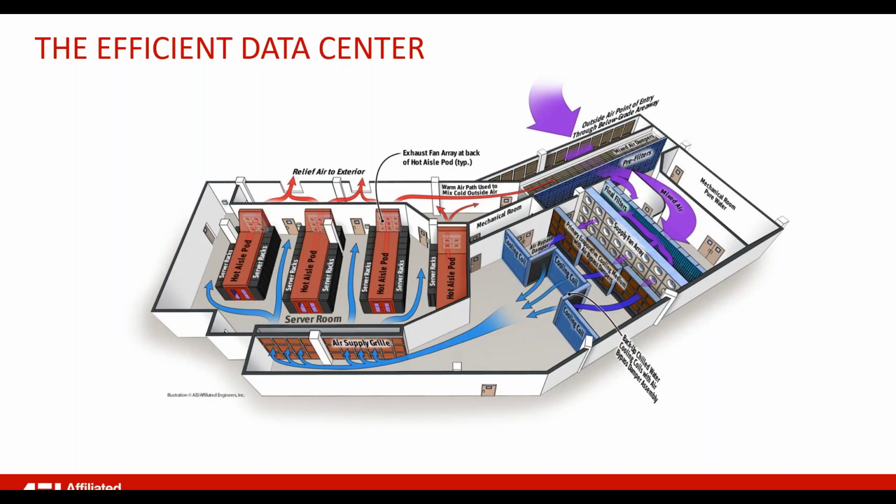While we talk about the traditional data center design, we'd like to also focus on the more efficient data center design, where maybe there's an evaporative cooling depending upon the climate. Again, the use of some form of hot aisle containment, and just delivering the air directly to the space to allow the servers to pull that air in. Again, looking at a pretty efficient type of data center here, using some type of indirect evap or direct evap to allow a compressorless type of data center cooling system. Next slide.